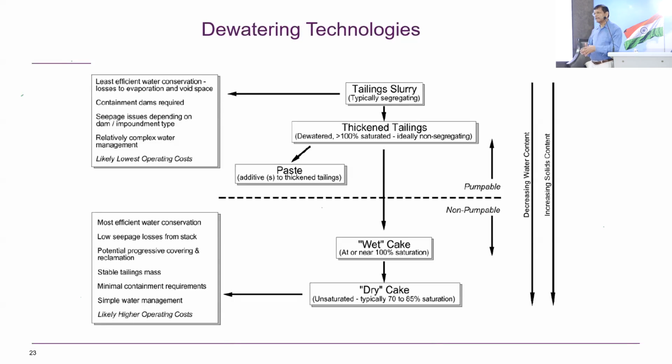Again, we also have other solutions. We normally put some berm in front of it to stabilize it. But as we saw in that failure, if it fails, that berm will not help either. So basically I told them dewatering is not easy. It will be expensive, though we can do some pilot testing. So I discouraged them from dewatering, and they went back to another consultant.